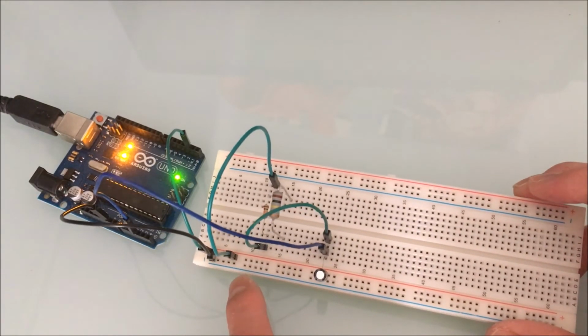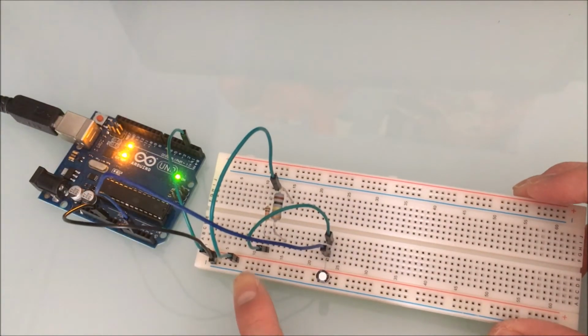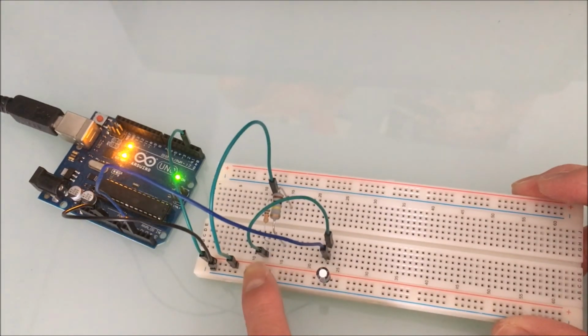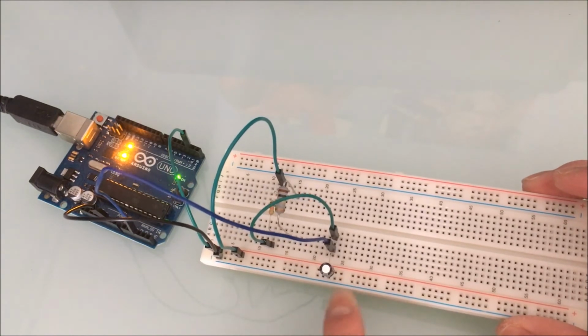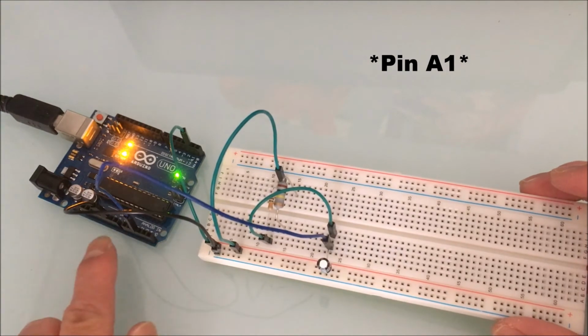This is the RC circuit. Power is supplied by the digital pin 2. We have a 10k resistor and a 100k resistor, and we can switch between them by moving these green wires around. We have a 10 microfarad capacitor which is attached to ground, and on the positive terminal we have a signal that enters pin A2.